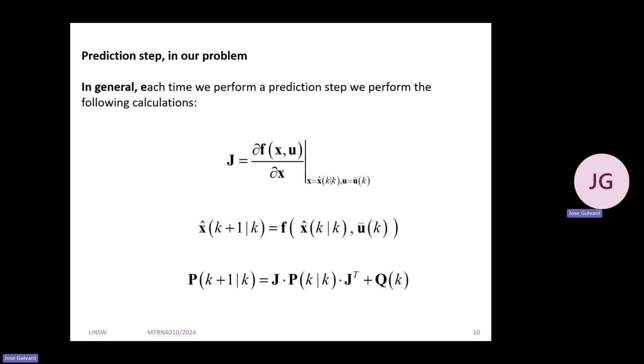Okay, now you need to have a prediction. Yes, I need to apply the prediction. Now, what do we need? I need a nominal state equation or a nominal process model, or whatever name you want to use. State equation and process model are the same for us. Yes, I do have that. So if you ask me to implement the prediction and get the new expected value one step ahead, I am working in discrete time here, and that corresponds to a 5 millisecond sample rate. I jump 5 milliseconds to the future, or from 5 milliseconds in the past to the present.